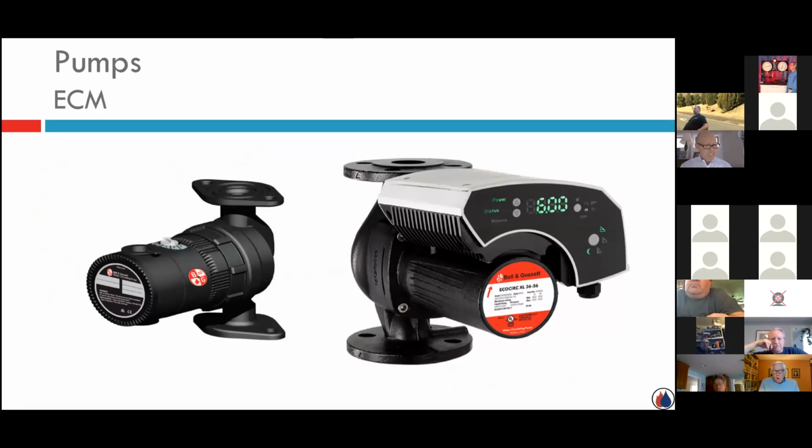ECM circulators, they're starting to take over North America, certainly over here in Hydronics Alley in the Northeast. It's becoming a very popular technology, and the utilities up and down the East Coast here are playing a big role in it. They see the value in the reduction in energy consumption, kW consumption, by moving to this technology. So it's still a circulator, still has an impeller, still has a motor. How they do what they do, though, is different in terms of having a drive, and inside here there's a printed circuit board, like a microprocessor. So all of these style pumps have some form of intelligence on board.